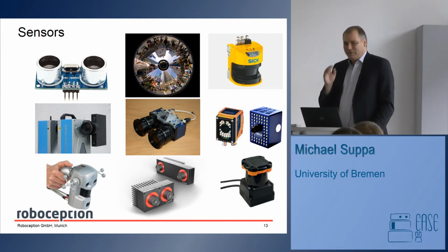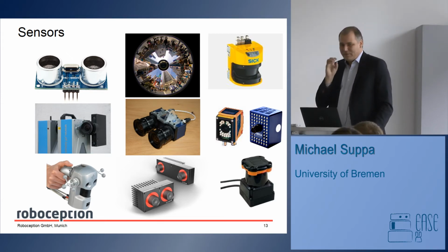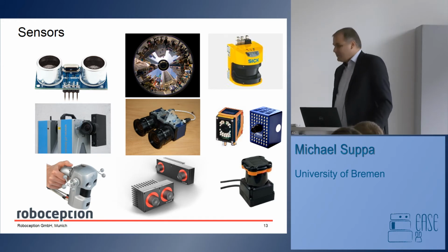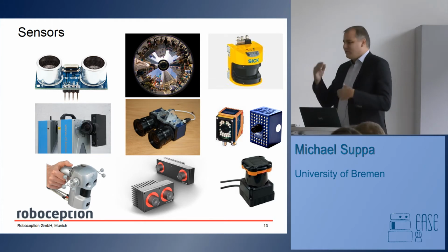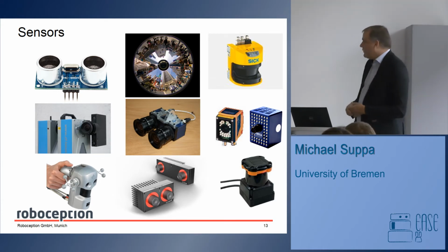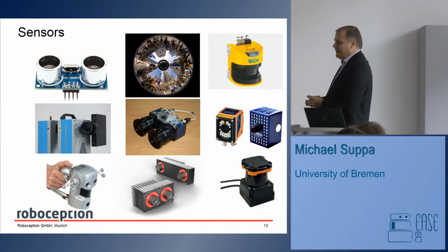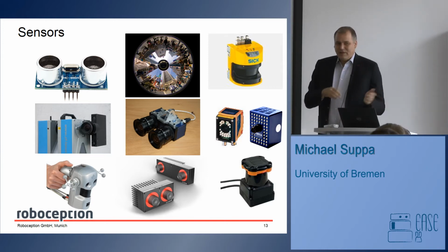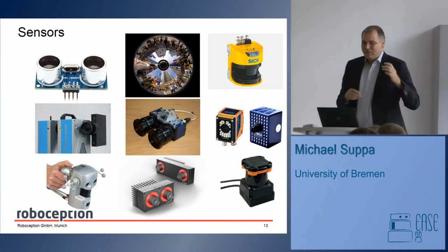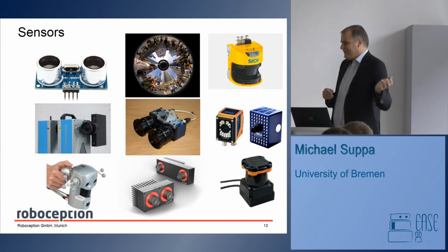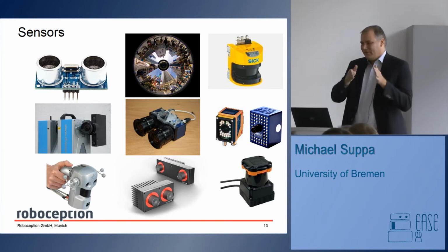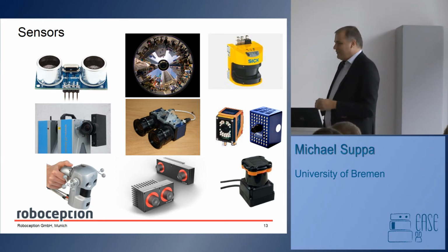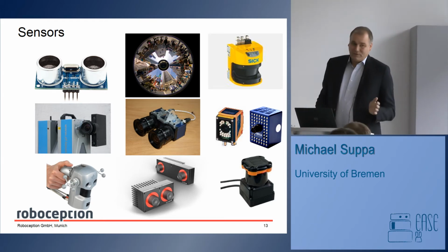You're getting your data from a physical measurement principle, and this physical measurement principle has errors. It has to be calibrated, and you need to know what kind of data you're getting. If you say, okay, I'm using Kinect, I'm not sure if the same algorithm you were using on Kinect data was ever tried on some other sensor, because if it doesn't work, it's probably that you modeled something which is very specific to that one specific sensor without knowing it.